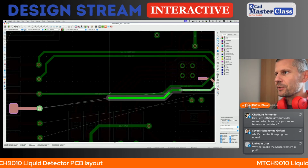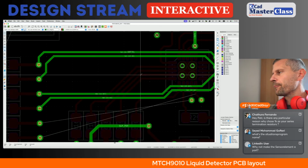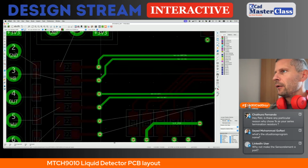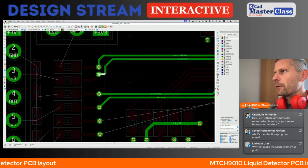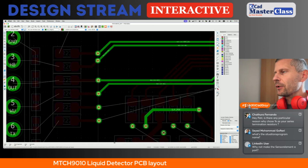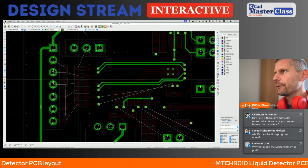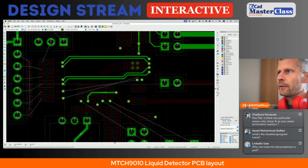We will use some stitching vias for the reference plane, for the ground plane, but I think if I use this trick, we will not need them, because the entry point here for the copper is quite enough.